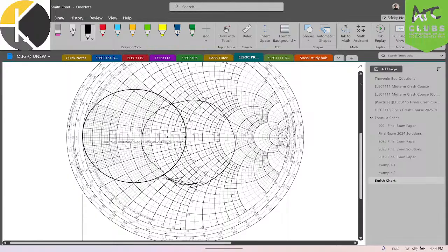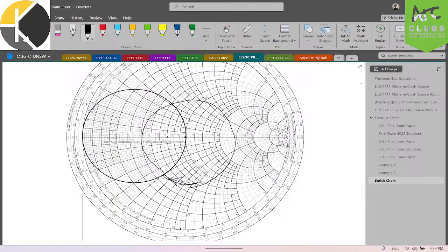You're going to move this way with a section of transmission line, and then move it this way along a constant conductance line to the origin, right? By adding a parallel shorted stub. But the problem is on this Smith chart you only have one side. You don't have your conductance circles drawn out. So you use your resistance circles as a substitute for those by reflecting your impedance through a virtual quarter wavelength length of transmission line.